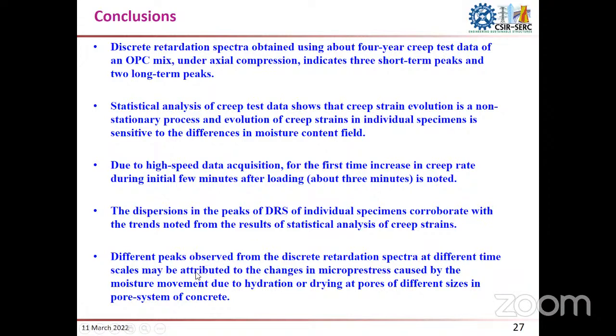Then these peaks that we observed in the DRS are due to change in the micropressures caused by moisture movement due to hydration and drying processes in pores of different sizes in the pore system of the concrete.